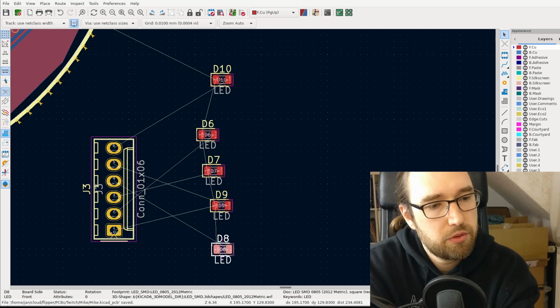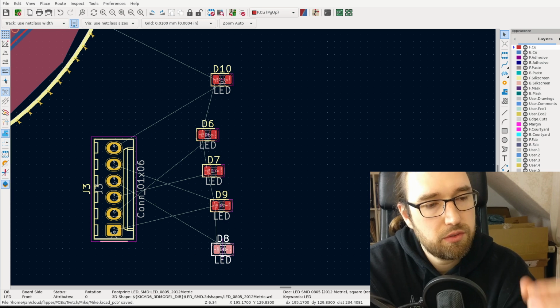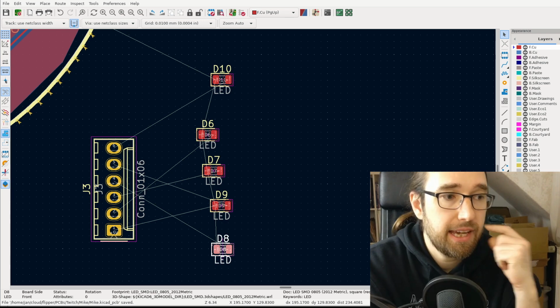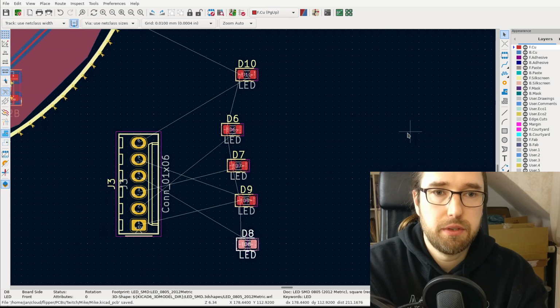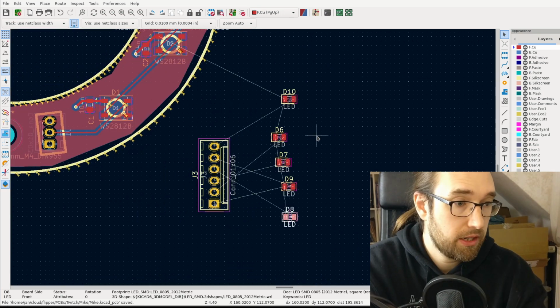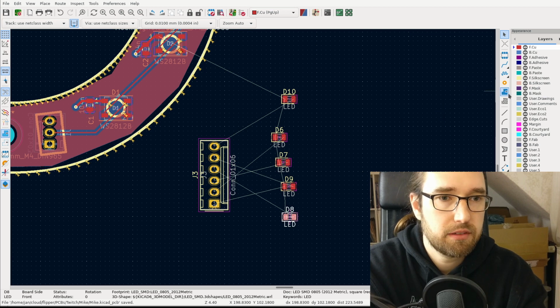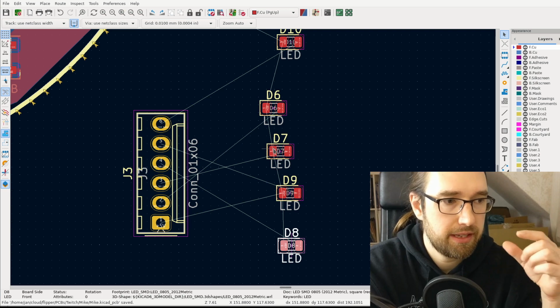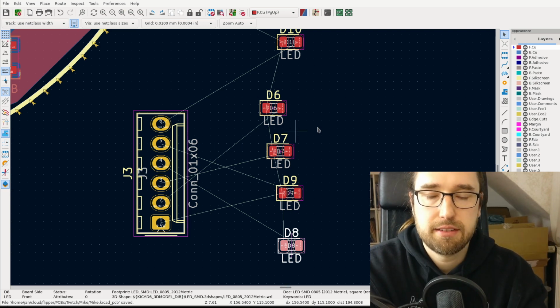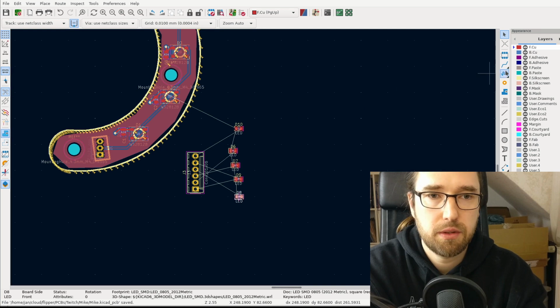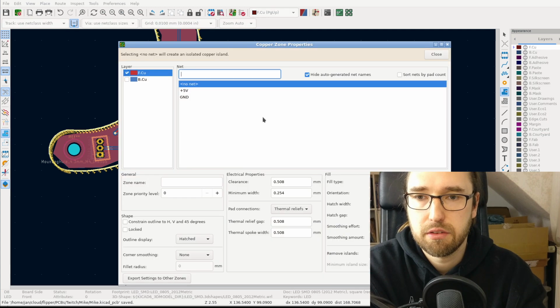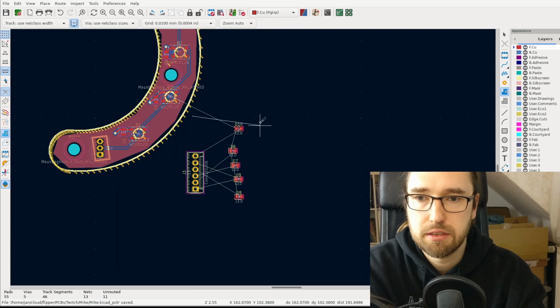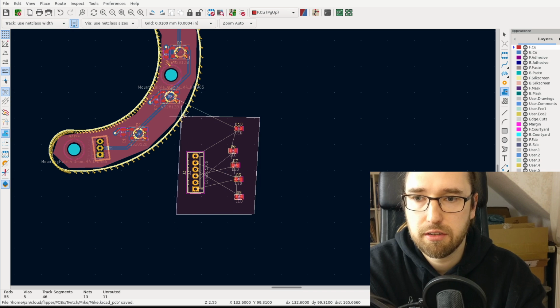If you drive parallel RGB, you have to be very good with traces to not overlap. So what I would do here, and correct me if you think I'm wrong, is have a 5-volt plane on both sides. I would put this plane on both sides, but then you can still use wires and so on. So let's put a plane here, 5 volts, check, check, check.